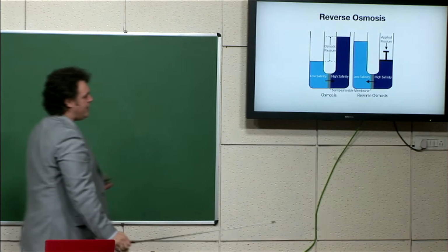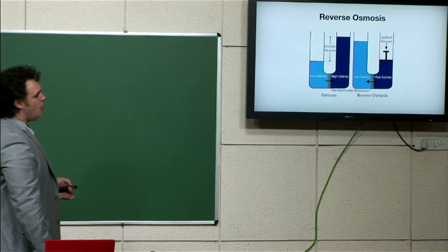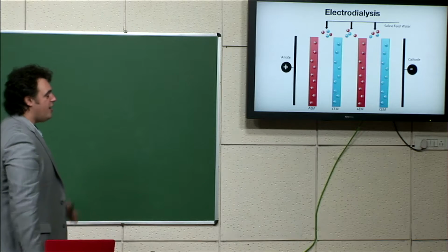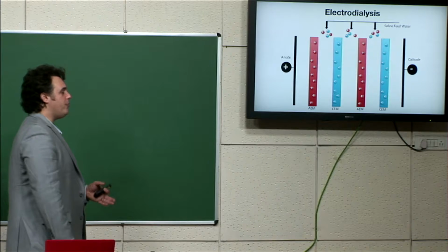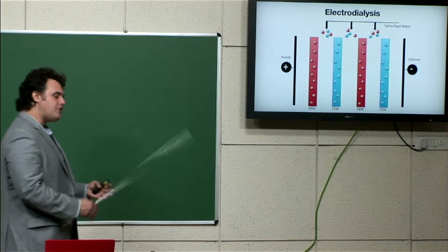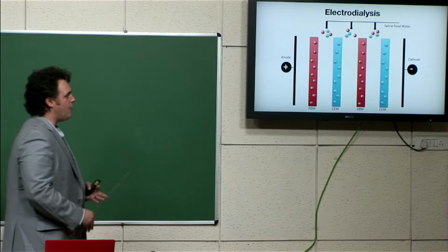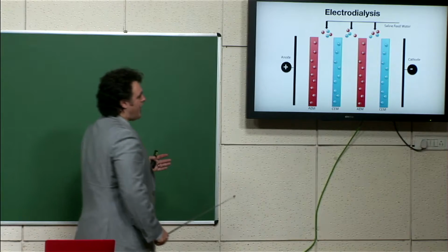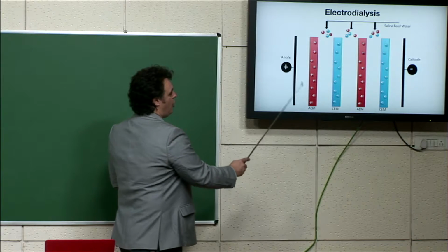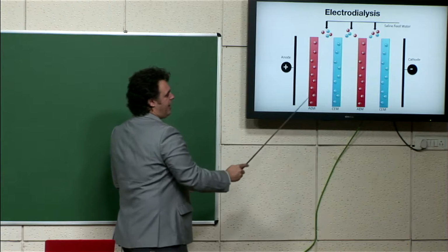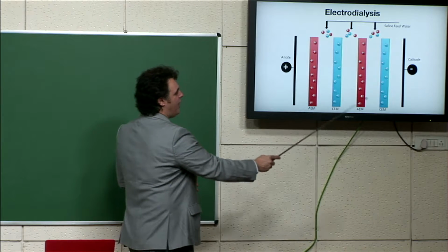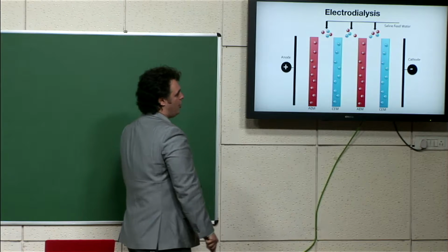So that would have been the de facto solution, but by understanding the technical space, we also understood that another technology could potentially be viable, which is called electrodialysis. The way that works is using an electric potential to move salt out of the water. And the way an electrodialysis stack is set up, this is called a stack, is you have alternating membranes, anion or cation exchange membranes, that can pass ions of one charge or another.